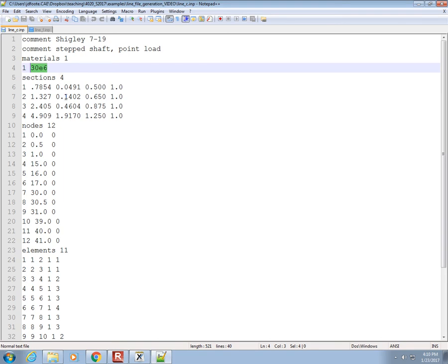So your homework problem is in SI units. In SI units, in this class at least, you always work with strength in megapascals, which since Young's modulus has units of strength, it also needs to be in megapascals, and it'd be about 207,000. Not 207 e to the 6. That would be, what would that be? I don't remember. Something else. It's 207,000 megapascals along with newtons and millimeters.